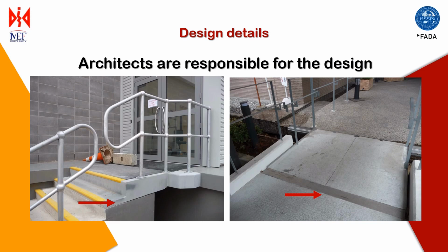An external secondary stair, the landing cantilevers from the isolated building to a right and slides on the supporting pier. The handrails are separated to allow movement.